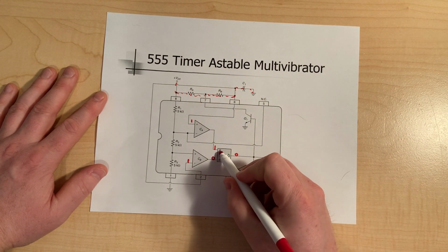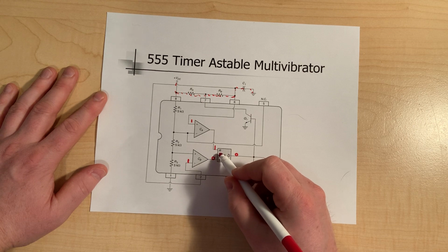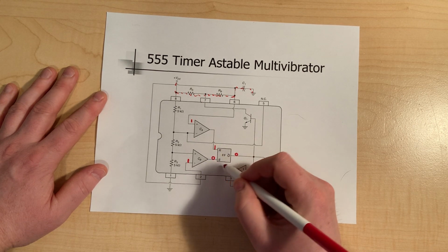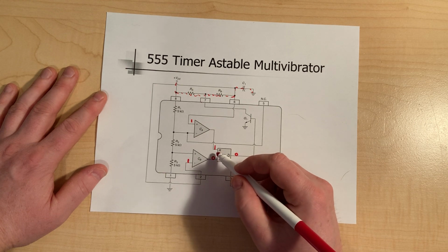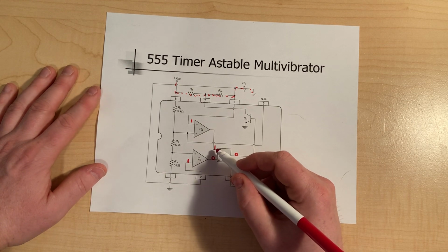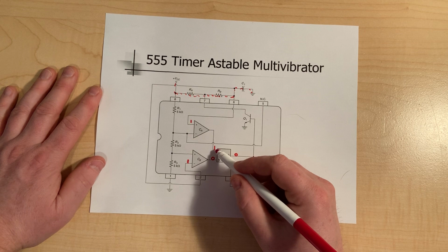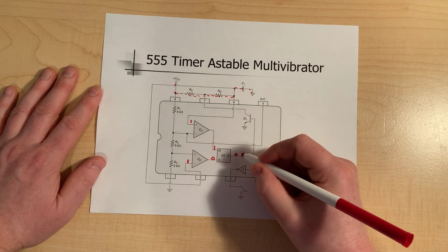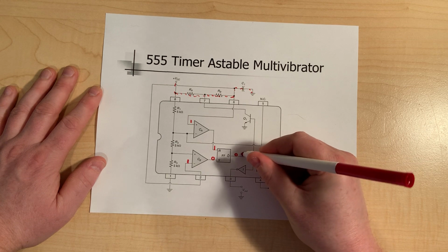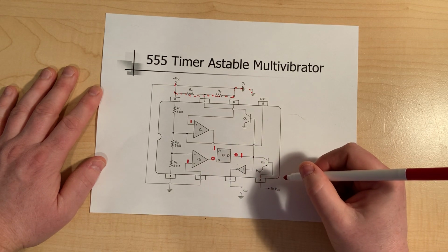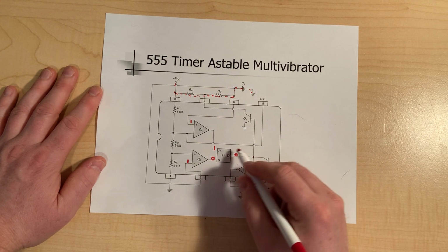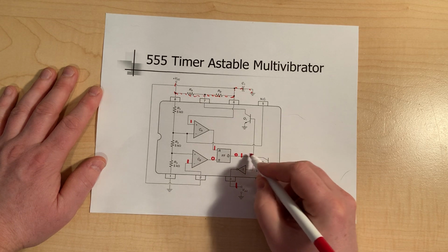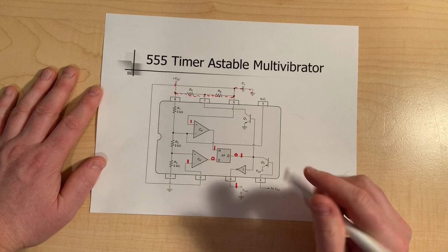Now, this is the reset, this is the set. If reset goes high in a standard, remember that this is a standard set reset flip-flop, where if it's in its normal inactive state, right, nothing changes. But now we set reset high, which also sets Q naught high. Okay, so now another thing to note is when we were low here, we actually had a high output. That output went high because we have an inverter here.